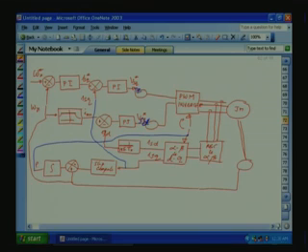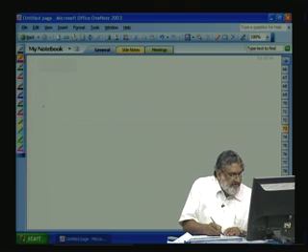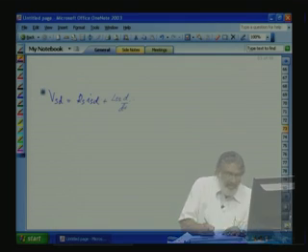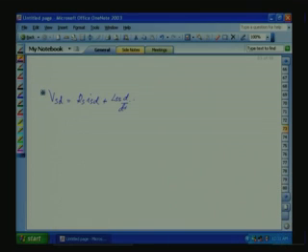But if you see the actual VSD VSQ equation, let us go back to the actual VSD VSQ equation. Here we can see VSD is equal to RS ISD plus, from the original, plus LSS d by dt ISD minus LSS omega s ISQ.